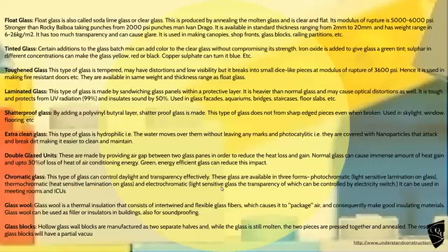Laminated glass, really good. That's what your windscreens are made of. You can use that for aquariums and staircases and stuff like that. Shatterproof, you put a polyvinyl layer in there, it won't shatter, you don't get sharp edges on it, and you tend to use that again for things like skylights and windows, especially windows which are within 900 millimetres of ground level to comply with the Building Code of Australia, so that if people stumble and fall against it, they don't hurt themselves. You can get extra clean glass, that's hydrophilic, the water just runs off them, very useful.